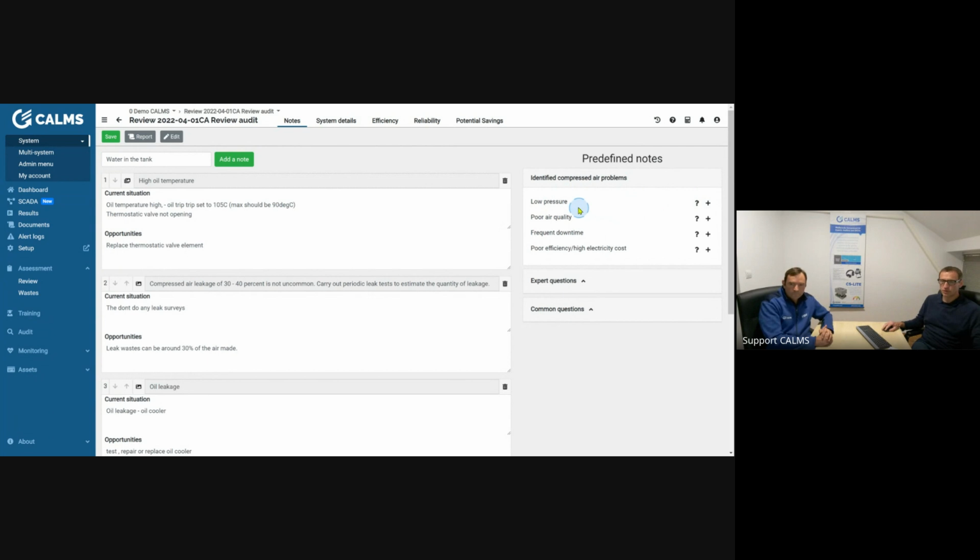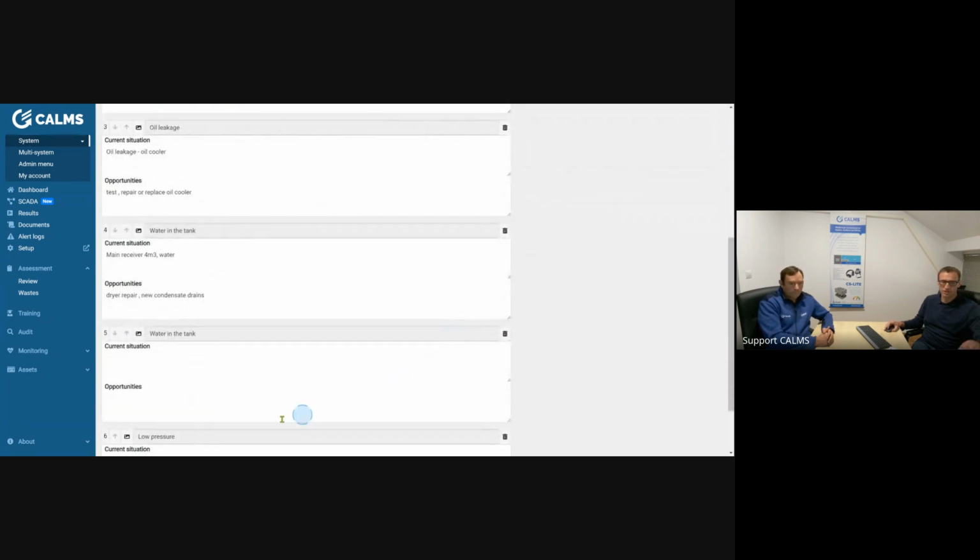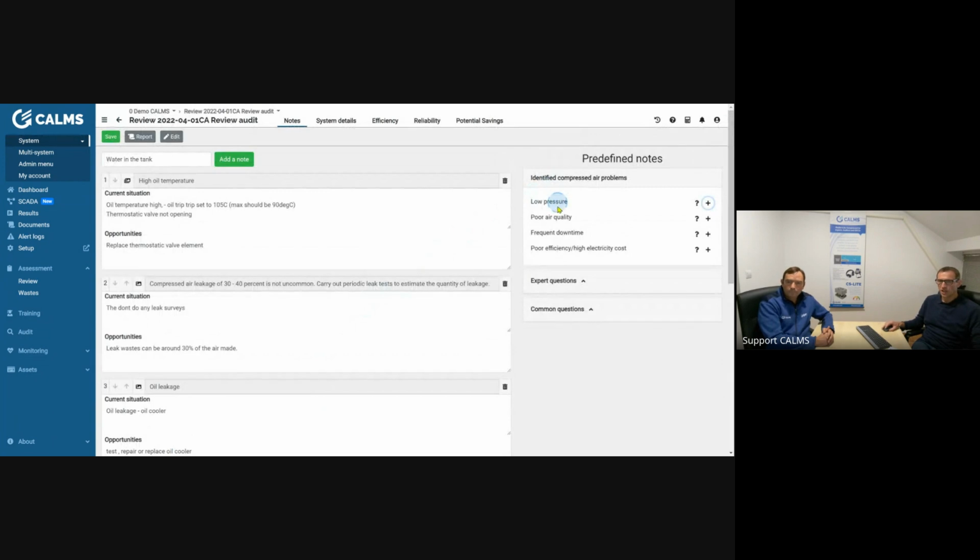But the most important is you obviously have a low pressure problem. I will put this as number one observation. It is here as a remark. You have poor air quality. You have water in the system, so that's also a problem. We opened the valve and we saw a lot of water coming up after the air treatment. So this is also a problem for you.